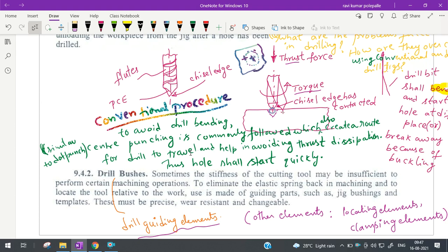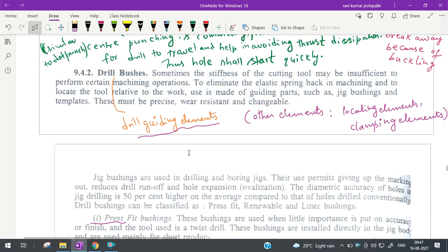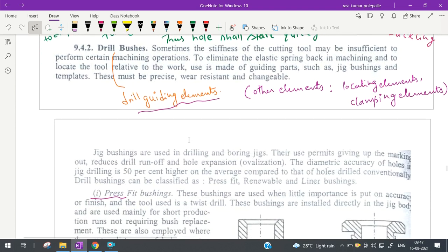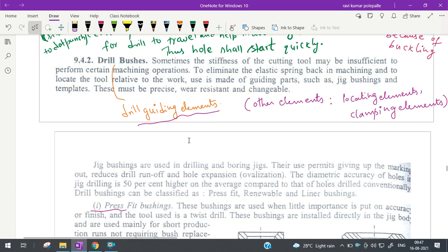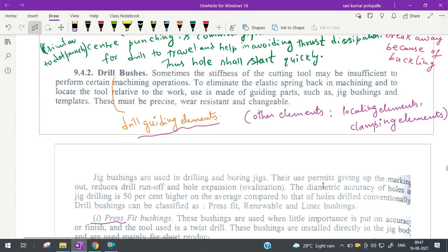So there are different types of drill bushes. Headless bush, we don't have any head. So simply they are press fit. Likewise, headed or flanged bush. The top of the bush is going to have a flange just to secure itself properly on the jig body.